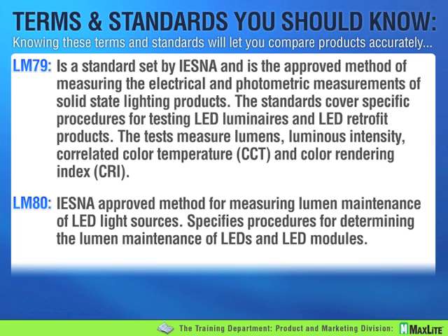You have all kinds of people walking in the door every day offering you LED products, say outdoor lighting fixtures as an example. One fixture is $200, the other fixture is $99. On paper, they look pretty similar. These are the questions we're trying to arm you with to start separating or weeding out the weaker products that are not living up to or can't back up the marketing data or the specifications of that product. So ask right away if the fixture has been LM79 approved using LM80 chips, and then you'll see how much of what you're considering is really not worthy of your customers' dollars.